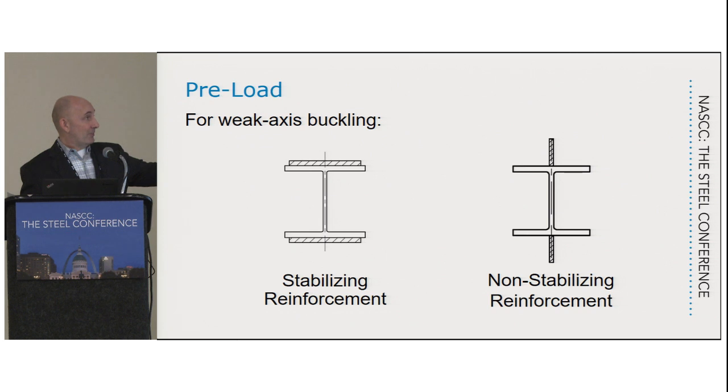Remember, we said we would come back to this one, the one on the right-hand side. The reason, and this is for weak axis only, is because you're adding almost no moment of inertia to this thing about the weak axis, and you're adding area.